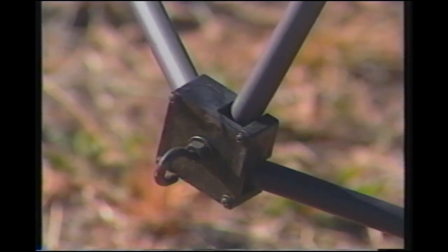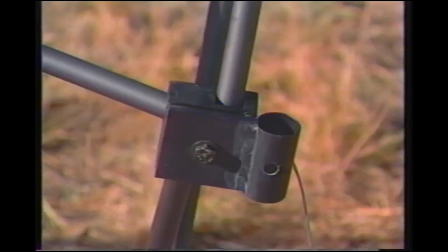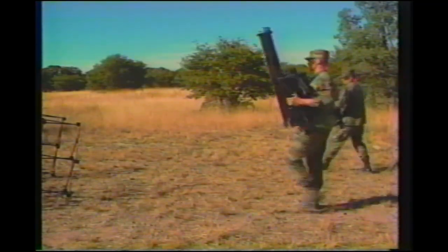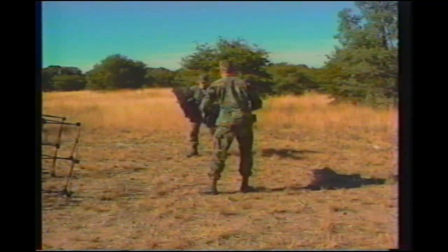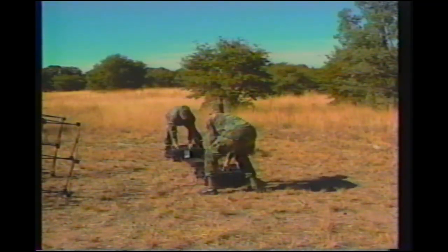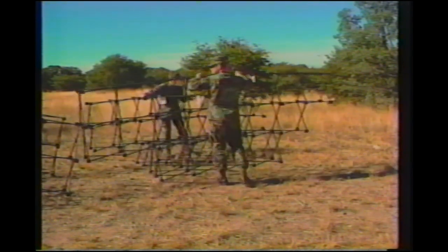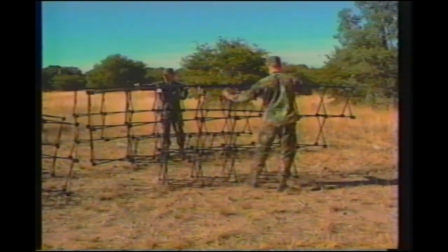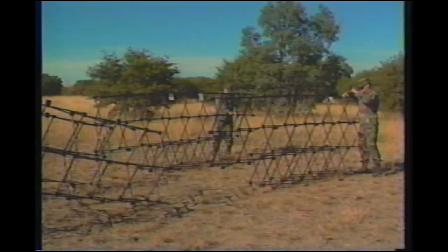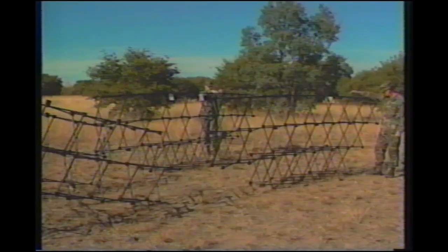The hooks go to the outside of the left and right frame sections, and the L-shaped frame collars go to the rear. Open the left and right side frame sections. Secure the 5 locking devices on each section.